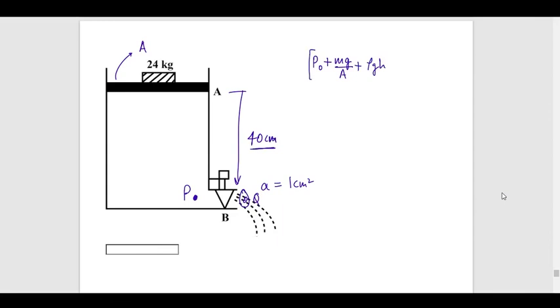So this is the total pressure present at point P plus the kinetic energy at point P, which is half rho v1 square, right? And that must be equal to the total energy at point Q, which has the pressure of P naught and kinetic energy of half rho v2 square.